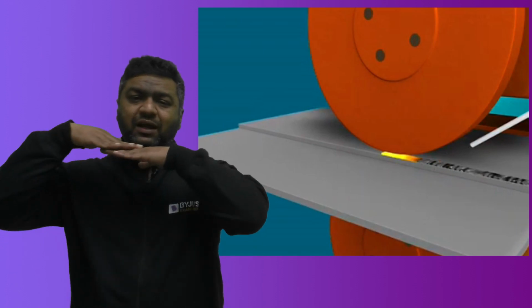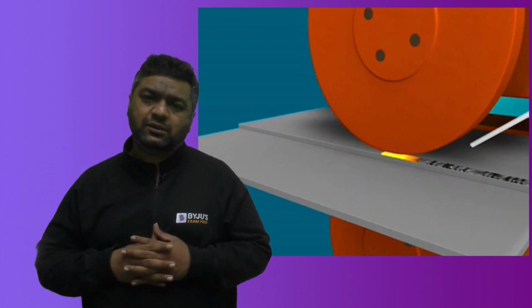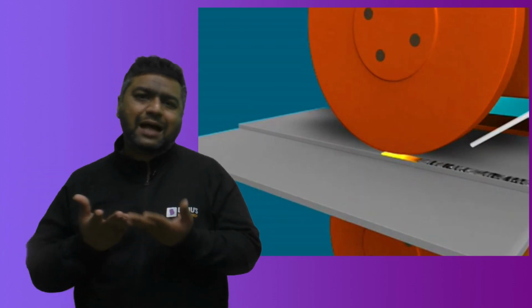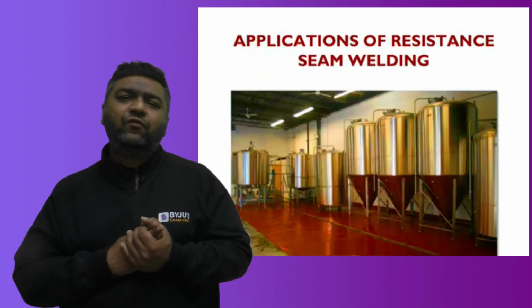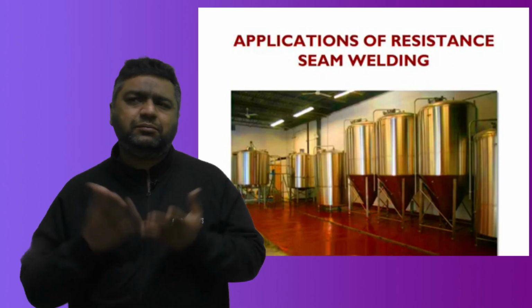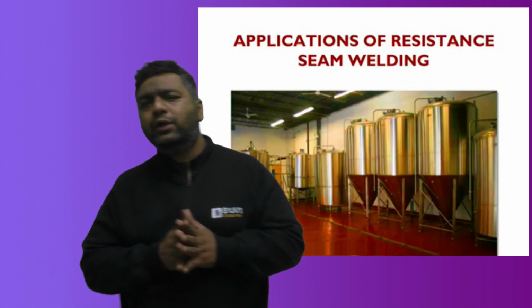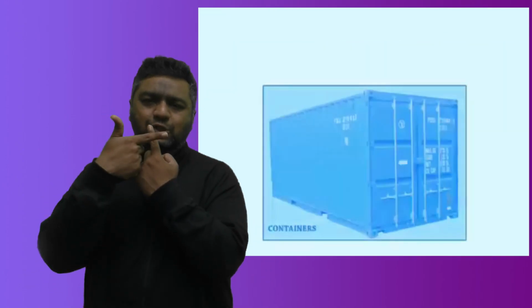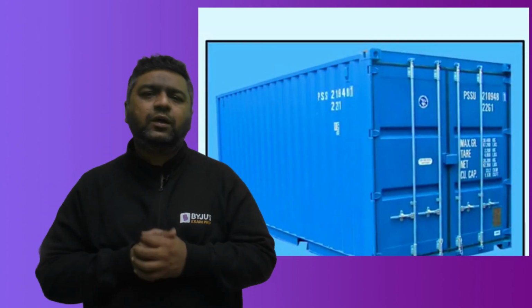Because of that, the weld is produced between the plates continuously. But as the current is coming continuously, some loss of current also happens, because some current may pass through the already welded portion, which is also called the shunting of current. This type of welding is generally used to make jali kind of structures, or any continuous weld where we want a leak proof joint, or to join wires continuously.